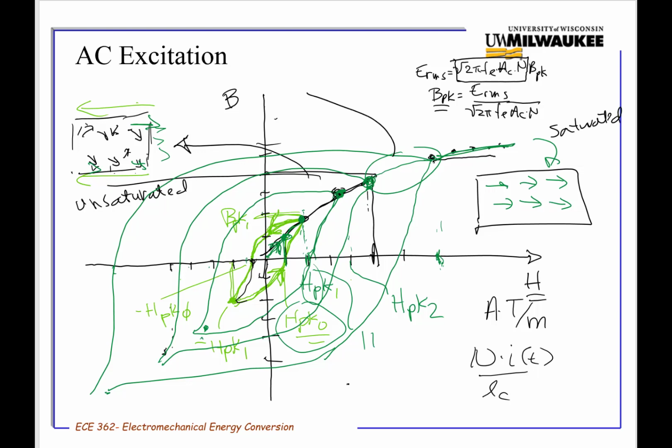And then you've got your knee point here, where you put about as much as you can into this. Normally if you're going to design something, you want to design to the knee point as the point at which you're going to get the maximum B max. I would call this B max, my target B that I want to operate at if I'm going to do a design with a particular core.